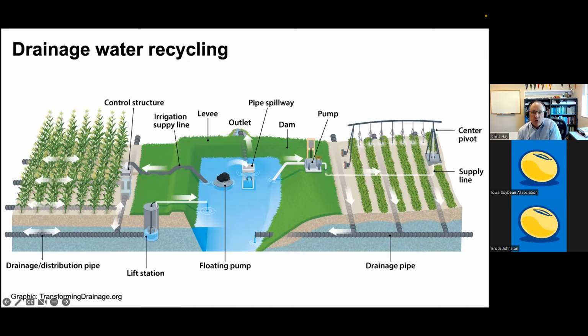As far as the reservoir, if we've got a good spot, a waterway or something where we could create an embankment dam, that's one option. In other cases, we may just have to excavate that storage and then build up a levee to create the reservoir.